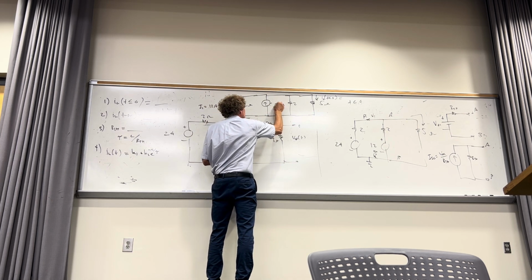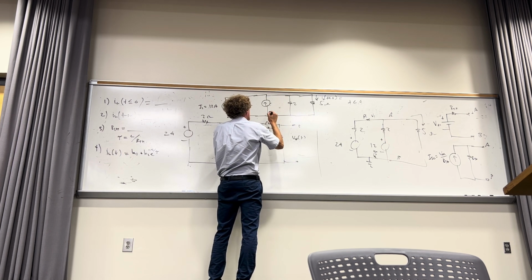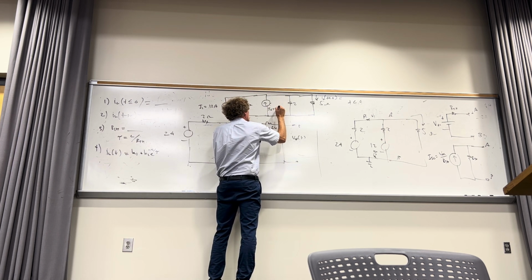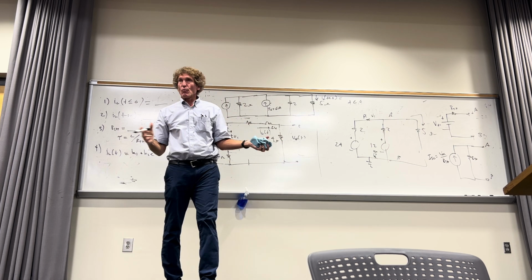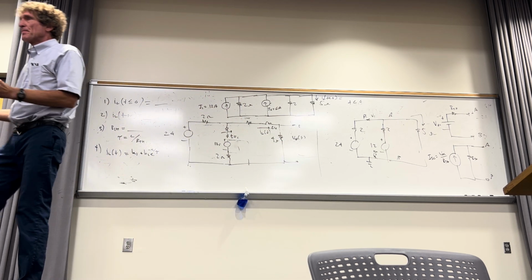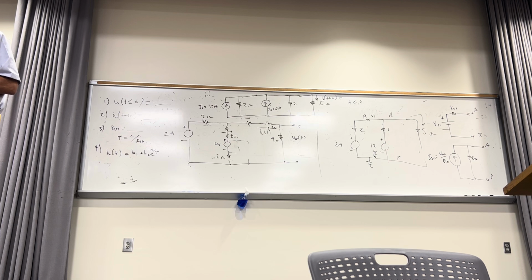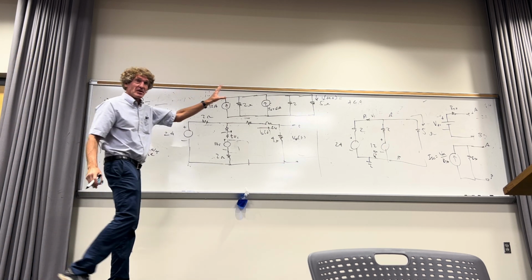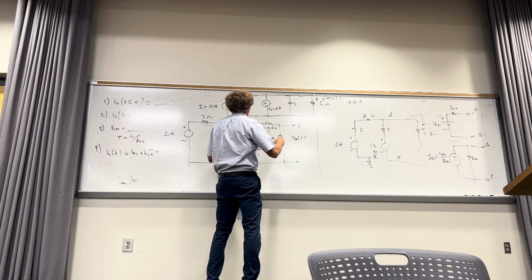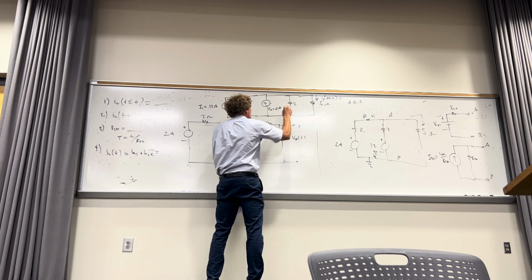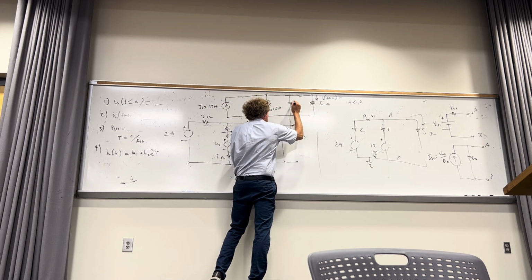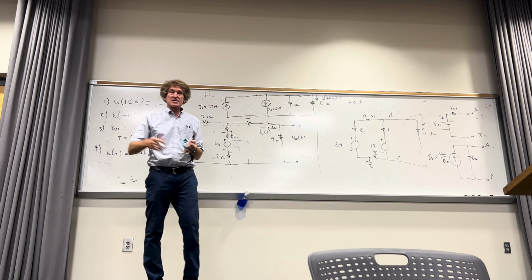Just making sure you can read my writing. Sometimes I can't. All right, now, we're not done yet. What else might you simplify? Take a look. How about 2 and 2 is 1 in parallel? You agree with that, down here, guys? I'm not trying to insult you. I'm just making sure. Maybe you can't read my writing, which is understandable. So this is really just 1 ohm, isn't it? It doesn't matter where they are, they're in parallel. Right? How many see that?